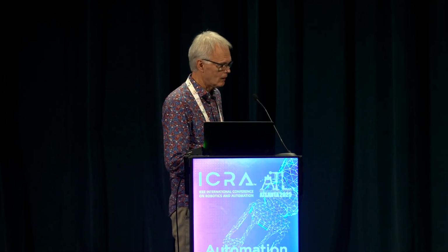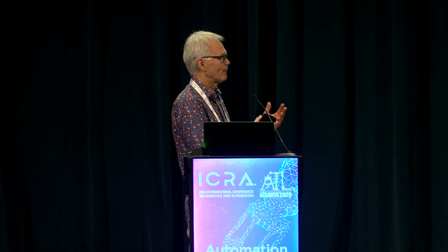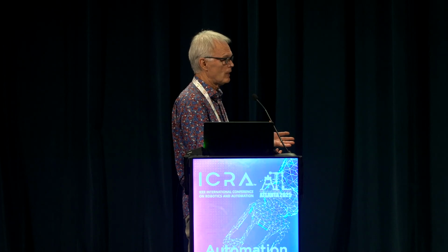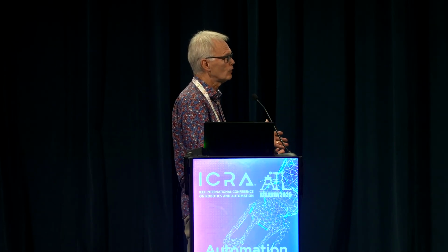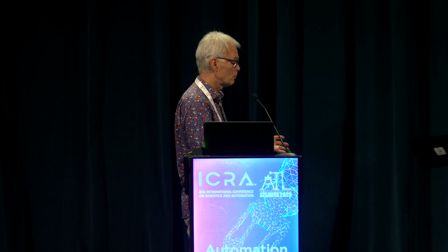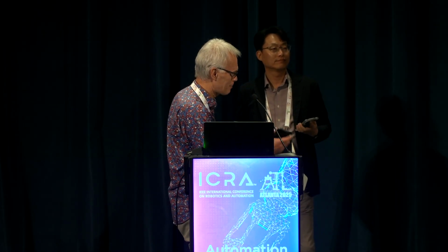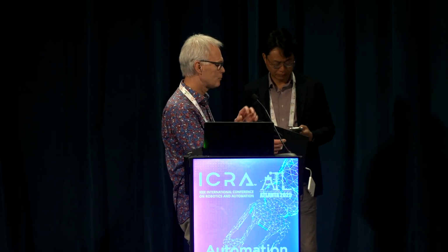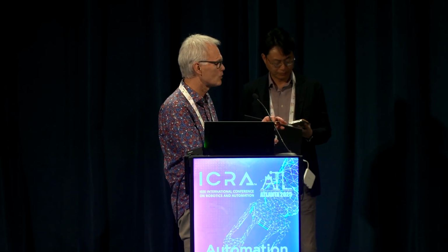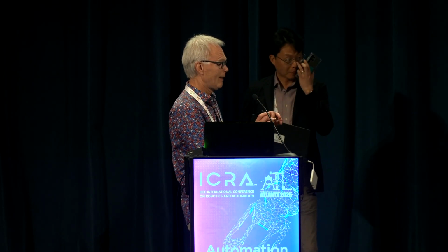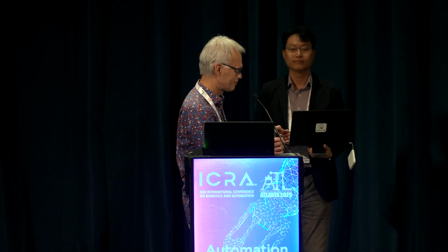Yeah, it's an interesting question about accuracy. You could say that the estimation of these models with our data, with this nonlinear system identification toolbox are very good, but it's still sensitive to these additional dynamics if you happen to have that. So we tried with one just extra small time constant, and you can see some influences also with the model-based version.